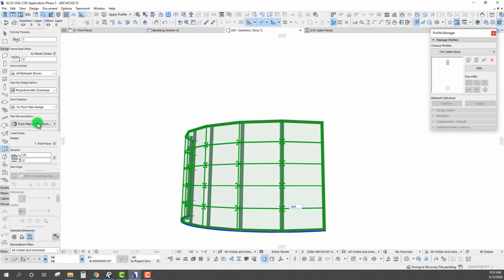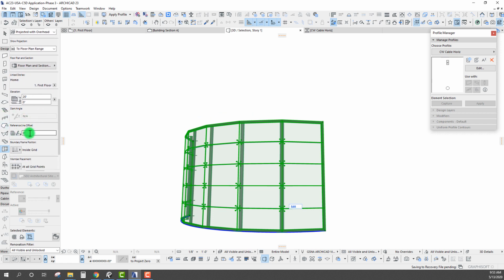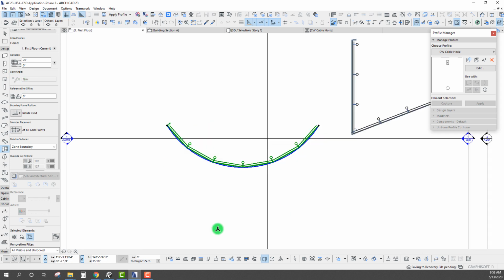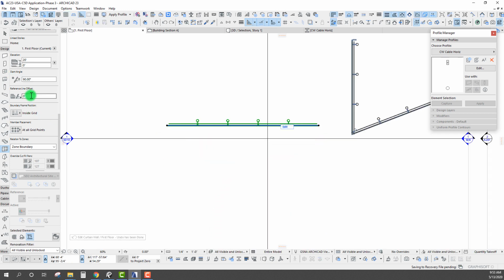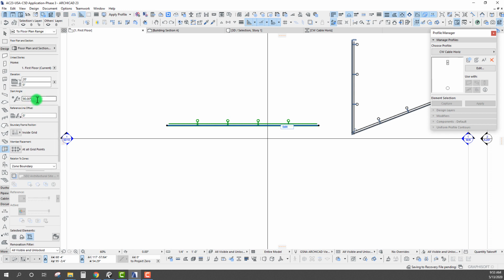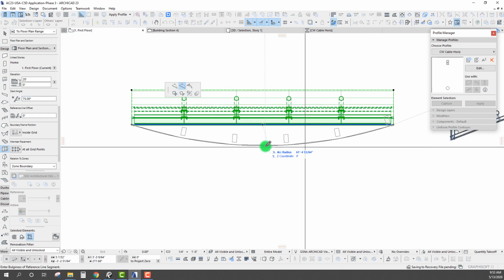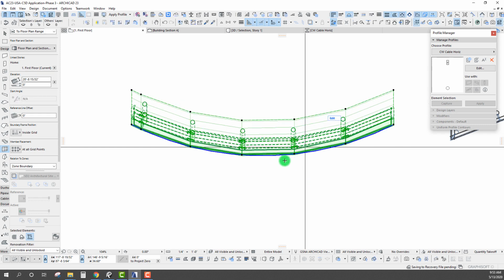We could always angle it a bit by, where's our angling setting? Slant angle, so it's not letting us right now. Let's undo that. Slant angle, we're at 90 degrees, so let's go say 75 degrees, and we can see how that's starting to angle. And then after we do that, we can radius.